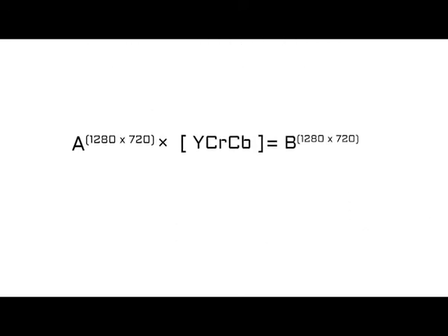We do this by converting each frame of our video stream into a matrix of values. We then convert our video stream into a YCrCb color format. YCrCb is helpful towards our goal of identifying how many rings there are because it gauges the intensity of red within the image. We also place two sub-matrices on top of each other into our video frame that we specifically analyze. We then determine the total number of rings by determining the mean of the values within the sub-matrices.